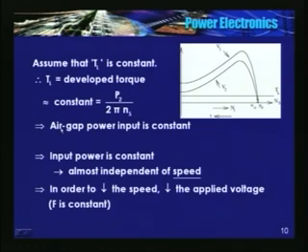Now this air gap power input is approximately equal to the input power itself. So therefore, what I can conclude is that the input power is almost independent of the speed if the machine is driving a constant torque load.